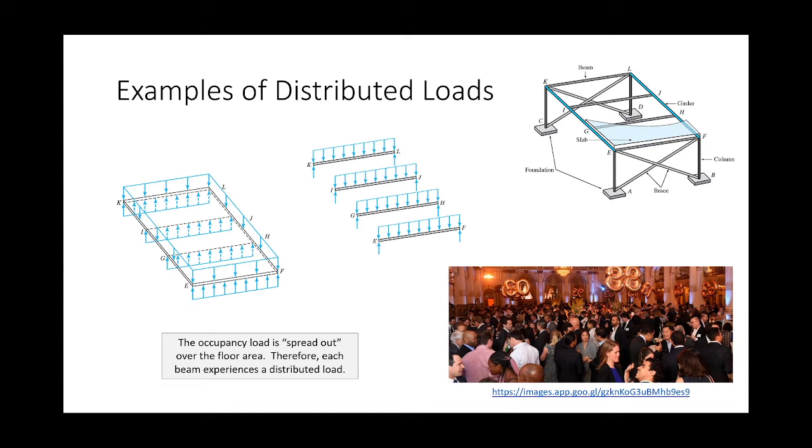If you design a commercial office building, like cubicles, think Office Space or something like that, the developer and the structural engineer might design the entire floor as if it's one big hallway, because the developer wants to be able to slice off certain components and rent it out to lawyers or dentist's offices or whatnot at X dollars per square foot, and they don't want to be restricted by where the halls are and where the rooms are. So they might just design the floor system as one big hallway. That's actually pretty common in spec office space.